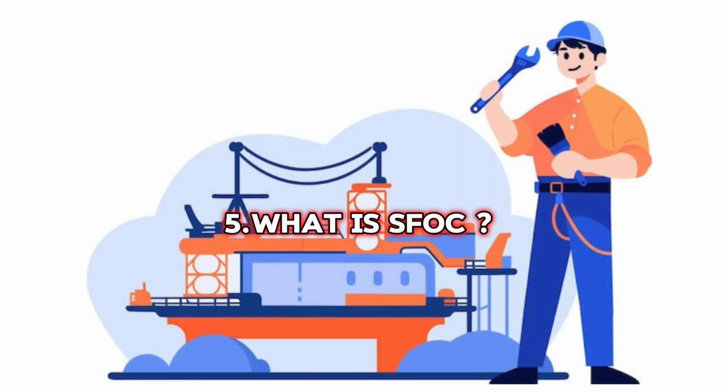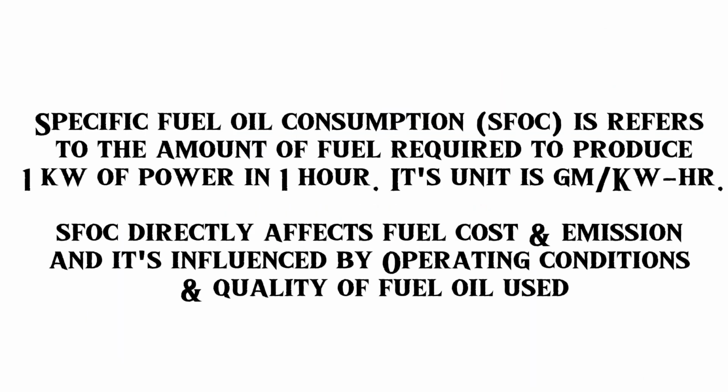What is SFOC? SFOC, specific fuel oil consumption. It refers to the amount of fuel required to burn to produce 1 kilowatt of power in 1 hour. Its unit is gram per kilowatt hour. SFOC directly affects the fuel cost and emission, and it is influenced by operating conditions and quality of fuel used.